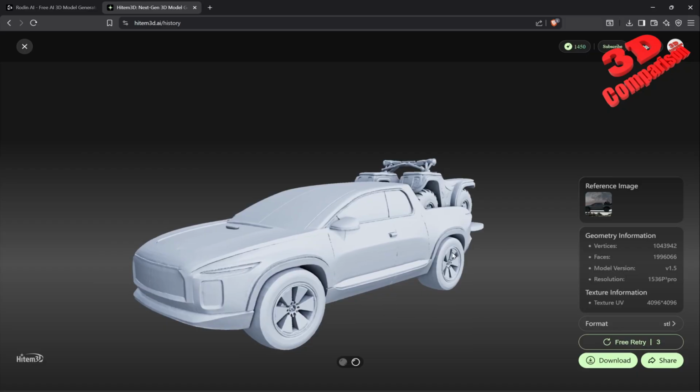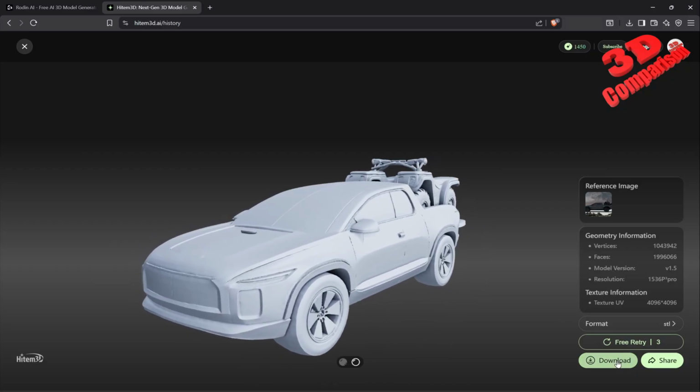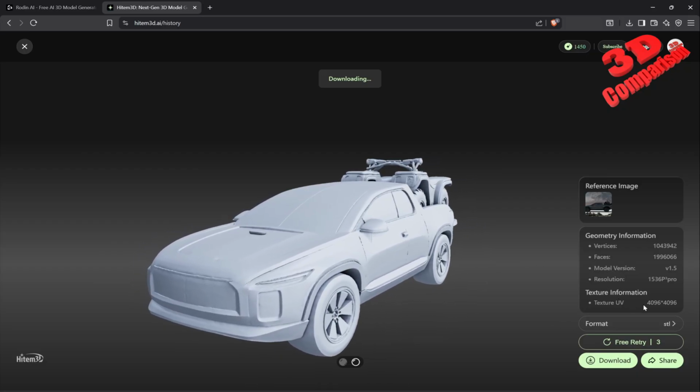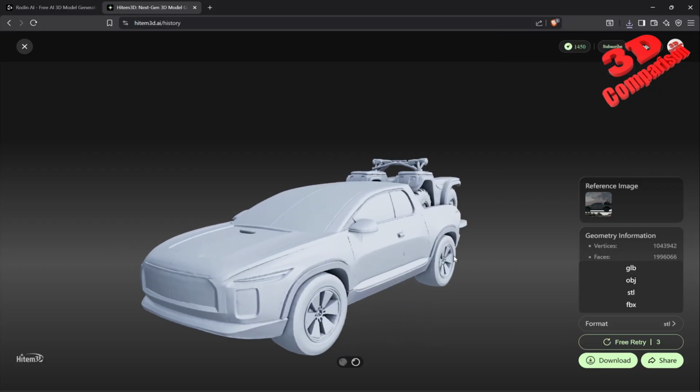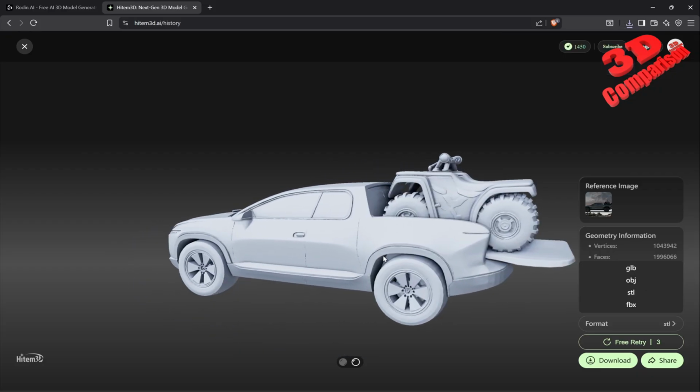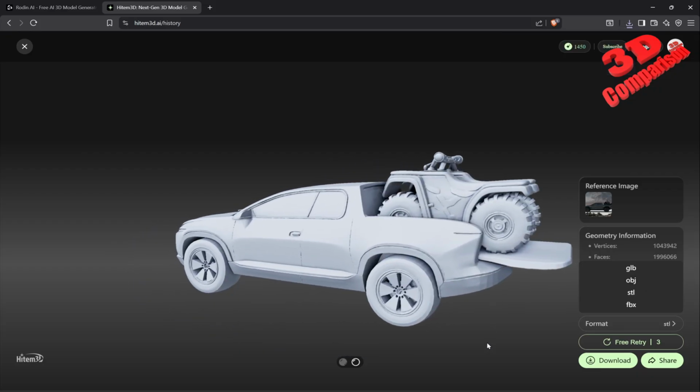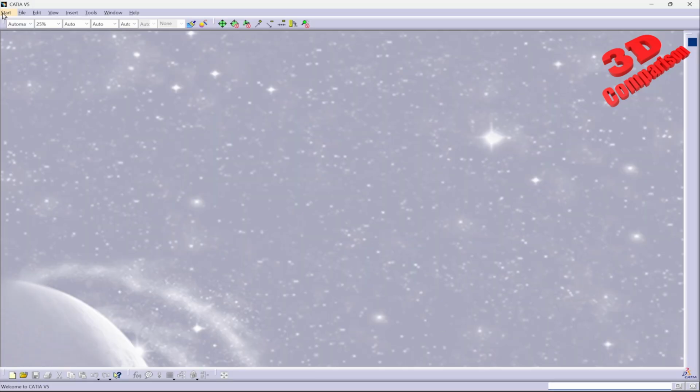Now, if I want to add this within CAD, especially within CATIA, I will need to make use of the STL file format. Within my previous video, I have shown you how you can also use the OBJ to import some of the elements as editable, but keep in mind that that will only work with low poly count. So in this case, more than 1,000 will be much more than CATIA can handle within Imagine & Shape.